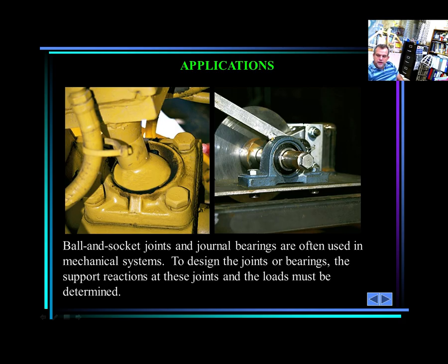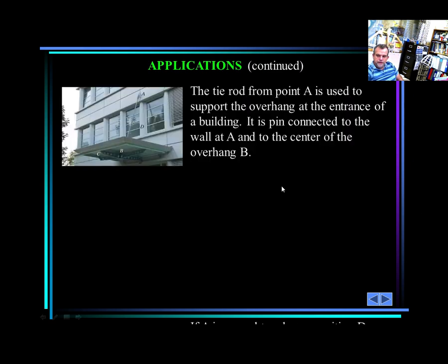What about this one here? Well, this is a bearing. If you see this bearing here, same situation. Cannot move this, cannot move here. Theoretically, depending if it's a thrust bearing, it cannot move in that direction either. But let's assume that it can slide. So you have 2 forces, and then you have 1 moment in this way and the other moment in this way. The only moment that is released is this one. So you have 2 forces and 2 moments for that bearing.